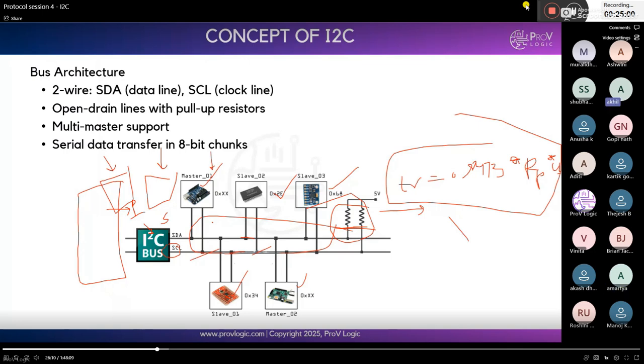Okay. So if I only have 2 pins, and I have multiple sensors outside the SoC, how will I know which one to select and which one not to select? Which master needs to select? Master will be the CPU, because it is inside the SoC. Microcontroller or CPU reside inside the SoC only.